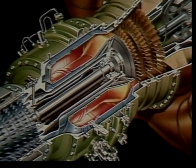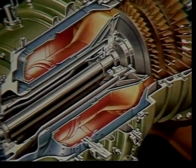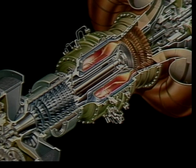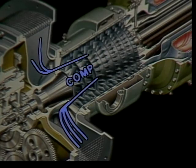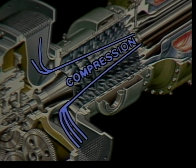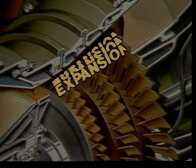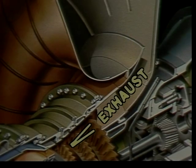It is in the ignition and combustion process that heat energy is produced and is converted into power useful for work. Continuous operation of the engine requires that 4 processes occur: compression, where atmospheric air is compressed; combustion, where fuel is added to the compressed air and ignited; expansion, where air and combustion gas expand through nozzles; and exhaust, where air and combustion gases are discharged into the atmosphere.